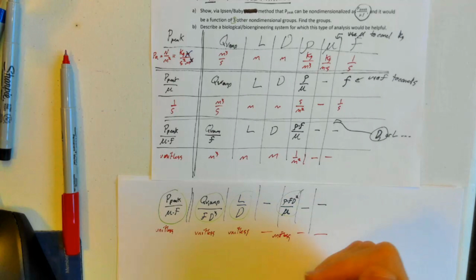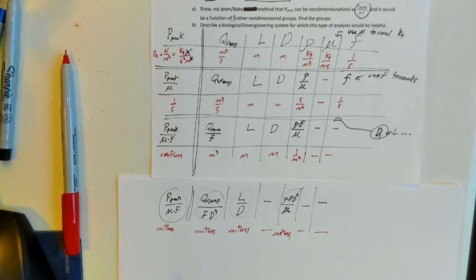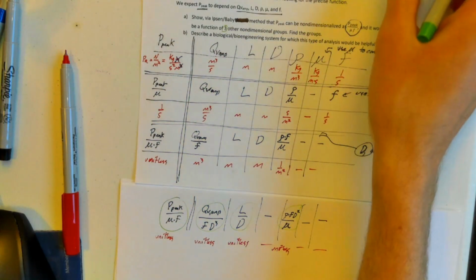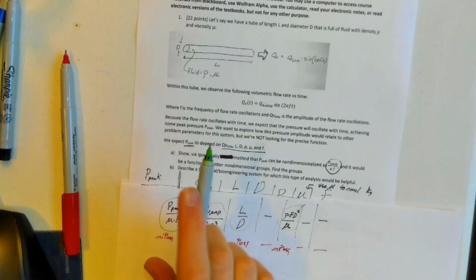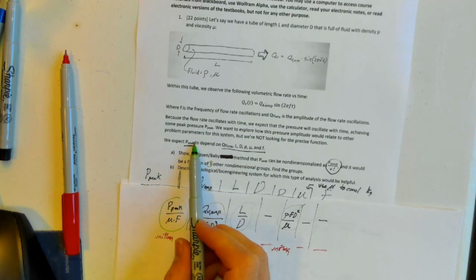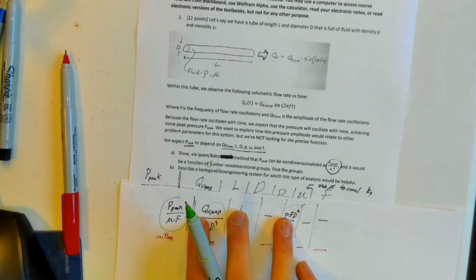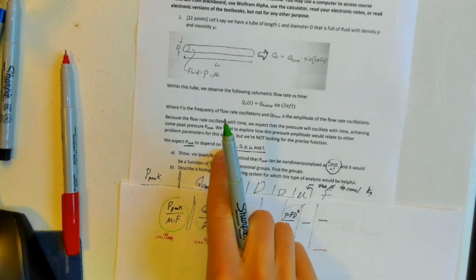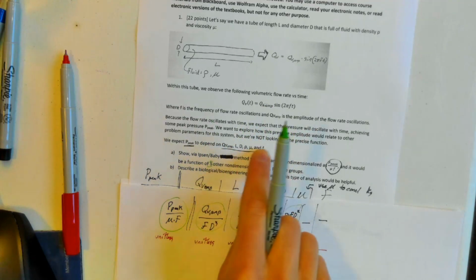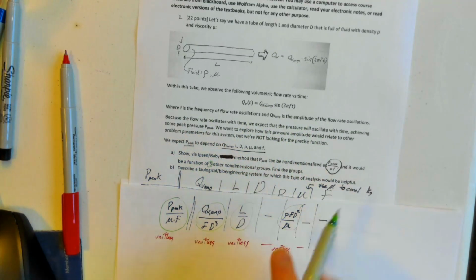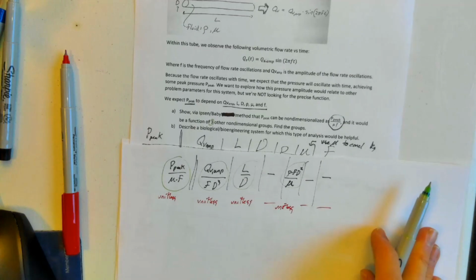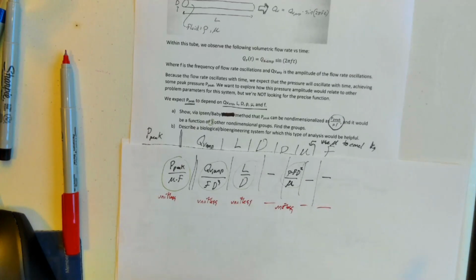It would just be a slightly different one, but I would still end up with three non-dimensional groups right here. All right, so that's this process of forming non-dimensional groups, and you can imagine, if we wanted to determine the relationship between these things experimentally, it would be a heck of a lot nicer to test only three different groups, three different knobs that I need to twiddle to affect the output, as opposed to 6 different knobs. So the benefits are in terms of our convenience for characterizing these things experimentally.